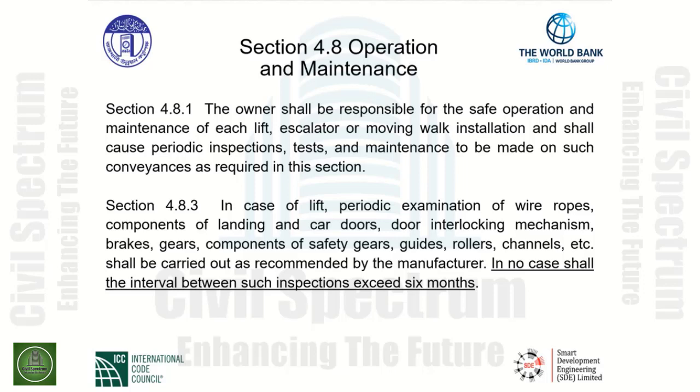Moving to Section 4.8.3, in case of lift, periodic examination of wire ropes, components of landing, and car doors, door interlocking mechanism, brakes, gears, components of safety gears, guides, rollers, channels, etc., shall be carried out as recommended by the manufacturer.